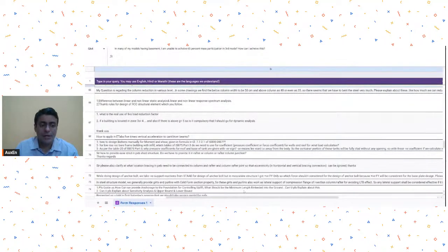But if you ask me, try not to put anything in the rafter column section, because there is always that problem of yielding also. So we may not like to have any other attachment at that location.